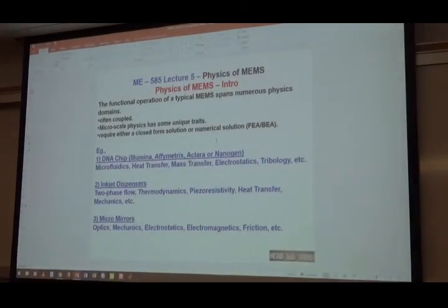Somebody was going to ask me, Omar. For the DNA, you say that you applied some voltage to make it move. Approximately, what's the voltage that you were applying to it? 5 maximum. And I'll tell you the reason. Arduino, for example, has a limit of 5 volts. So anything with integrated circuits is limited to 5 volts. So the limit is because of the Arduino's capacity for high voltage? Well, yeah, integrated circuits, but the DNA also gets fried. So you don't want to apply too much voltage. You want to apply just a little. Okay, that's a good question.